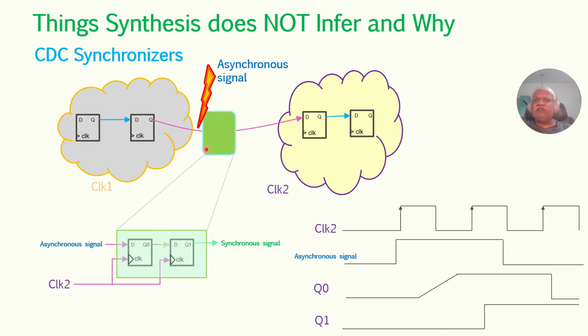So you can see how the asynchronous signal has been properly captured. The waveforms of this metastable condition will vary. Sometimes they will move for a very long time in the middle path and then reach, and sometimes they vary in the middle path and reach the bottom. There will be multiple ways in which this asynchronous metastable behavior will happen.